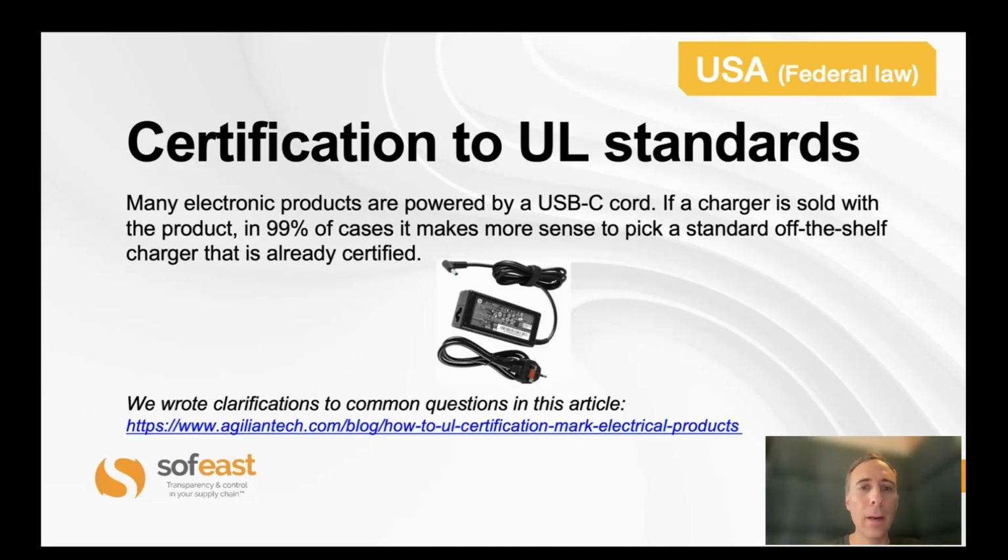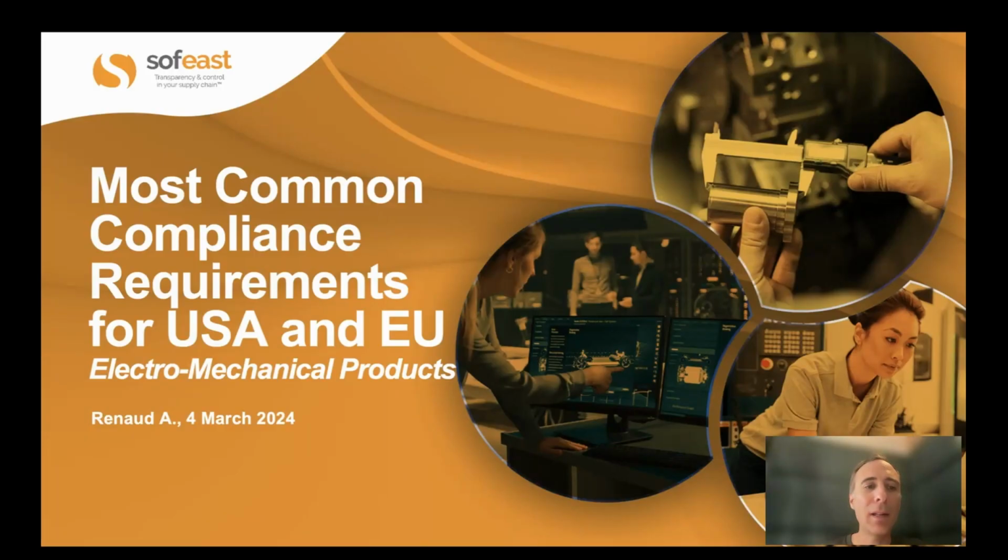Just a few tips here: if it's an electronic product that you sell, try to just provide a USB-C cord. Don't sell the charger, or if you sell the charger, pick an off-the-shelf charger that is pre-certified. And that's it for the quick overview of the main compliance requirements, again, about electrical safety for electromechanical products.